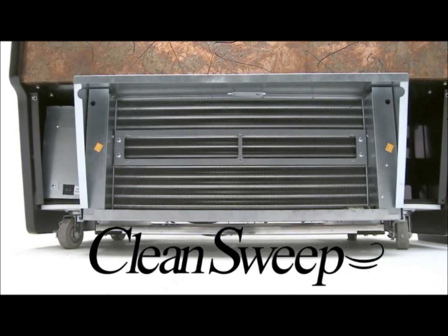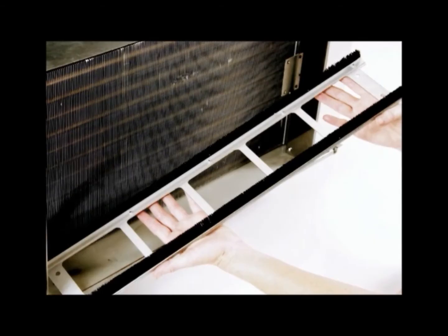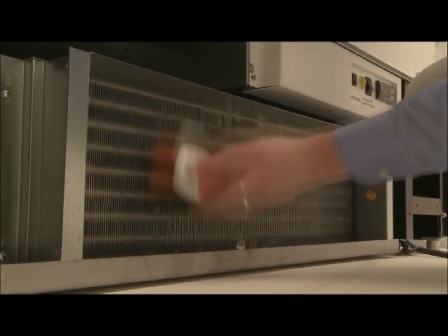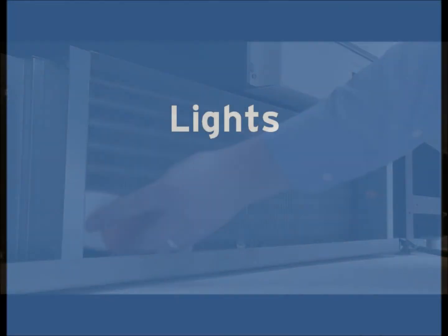If your case comes with our clean sweep option, you do not have to manually clean the coil to ensure proper ventilation. Without the clean sweep option, it is very important to clean the coil at least once a month, depending on the environment that your case is running in.